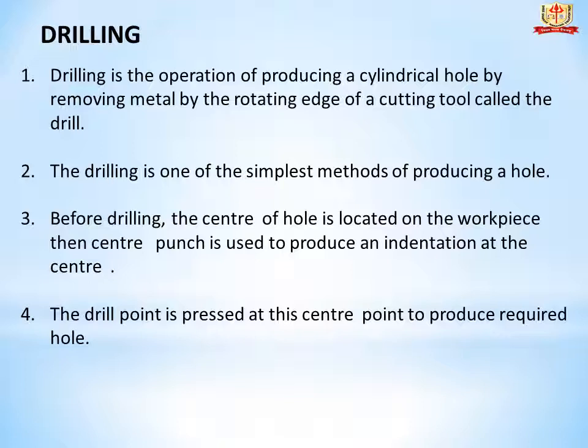Third, before drilling, the center of hole is located on the workpiece. Then center punch is used to produce an indentation at the center. Fourth point, the drill point is pressed at the center point to produce required hole.